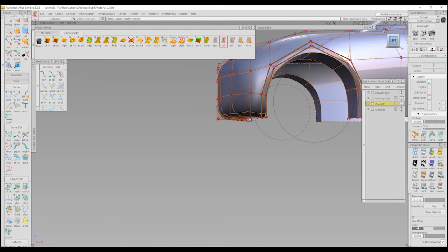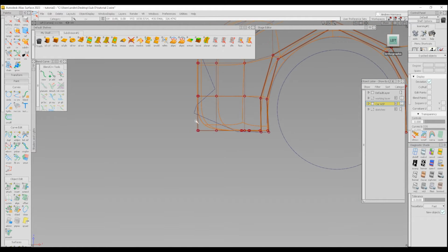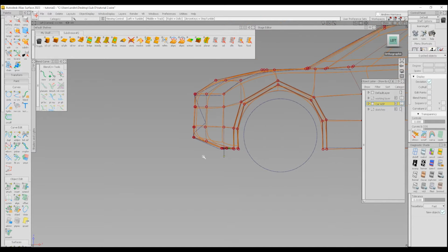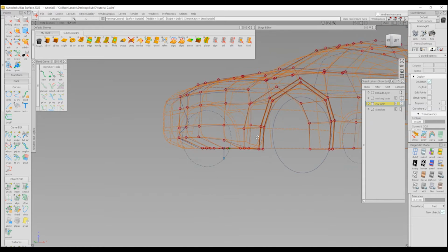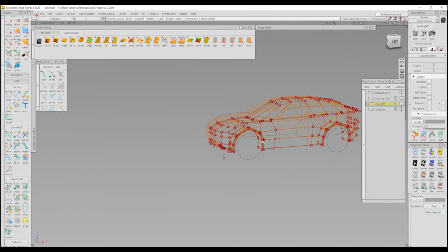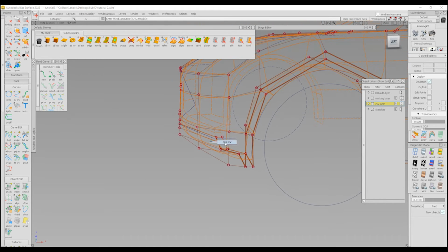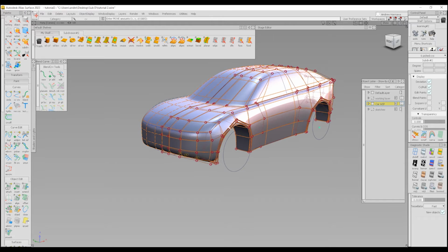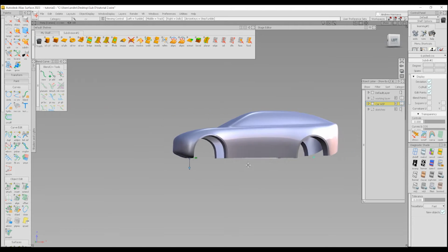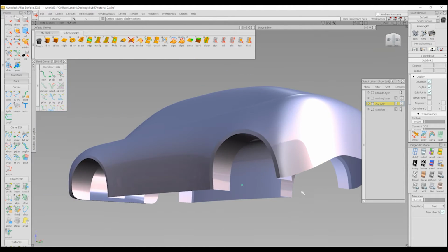And then I can go into the side view and look at my curves, and I can adjust the front a little bit, just like that, to get a little bit more accurate. And that's kind of like doing the approach angle for the curb. Okay, I can select these CVs and move them a little bit backwards to get a more uniform shape here. So now that looks like that. And then now I'm going to do the same thing in the back.